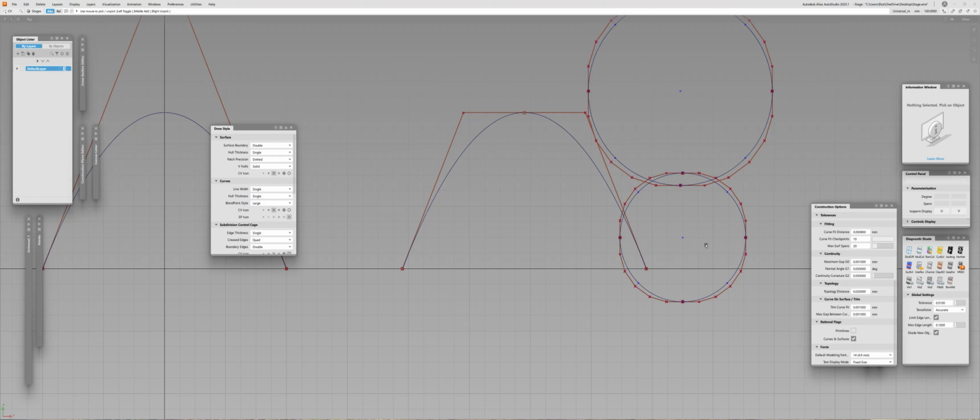So Alias automatically knows that to create the proper form, to create it ideal, to create the perfect radii, just B-splines are not enough. You need this additional tweak for the weights to really create the perfect radii. And in fact, if I take the radius here, you're going to see that it's literally spot on. That's because we are under the rational flags, because this circle is constructed through the NURBS curve at full potential.